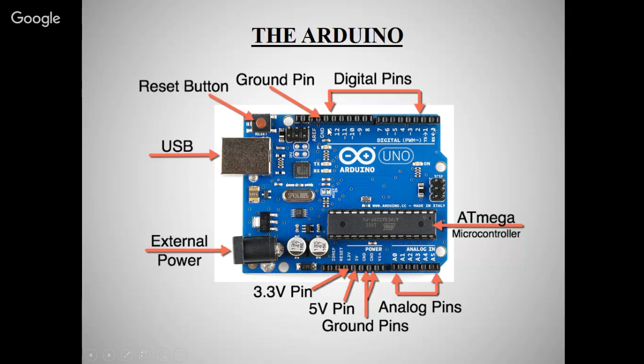You can see this is the inbuilt LED in the board for checking the first LED program, the blinking operation, to see whether it is communicating with your laptop or not. If the blink example is running smoothly, then you can say that my Arduino controller is communicating with my laptop. If there is no communication, then maybe there is a problem with the board, or with the software or drivers. There are many problems. So it is suggested that you first check the blink example on the Arduino, and after that you can make the bigger circuit.